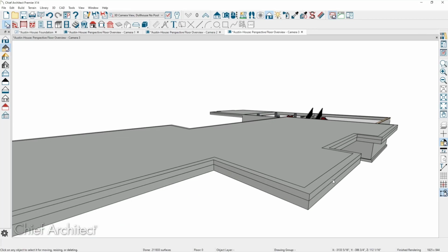So that's what happens when you try and put a slab footing underneath the slab, it does weird things because it tries to put a stem wall on top of it. My workaround is I'm using a 3.5 inch stem wall for my thickened slab beams and just showing the footing, even though I know it's not right 3D graphics. Nobody is ever going to look at it but me. Sure. But it's basically an 8 inch thickened slab with 45s at the bottom, 2 foot wide.